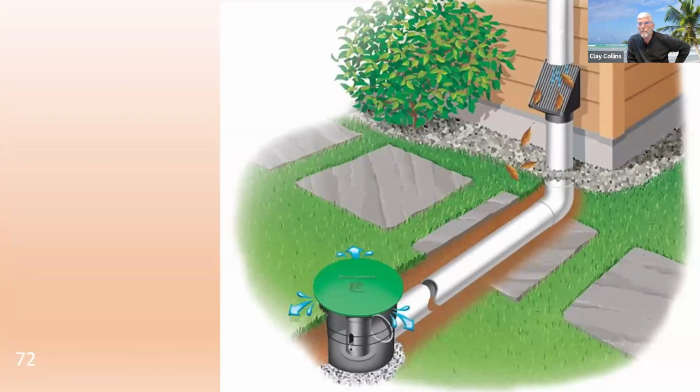Subsurface drain. Now, you'll notice that that's a pop-up. I may mention this in a little while, but municipalities don't allow you to cut the curb the way you used to. Okay, Jeff was quoting some code there that directly addresses this, but you'll see the excluder there.